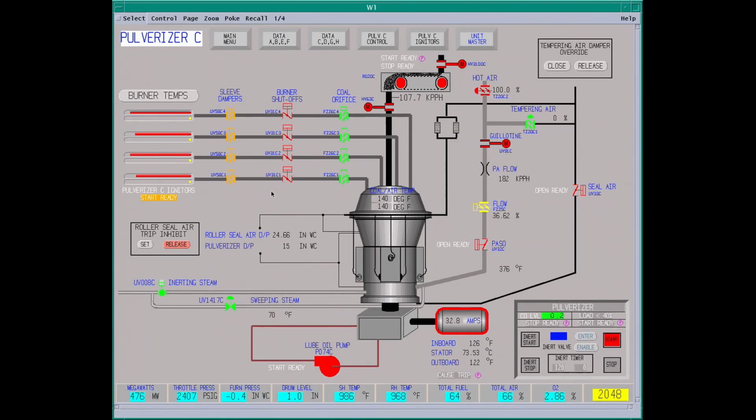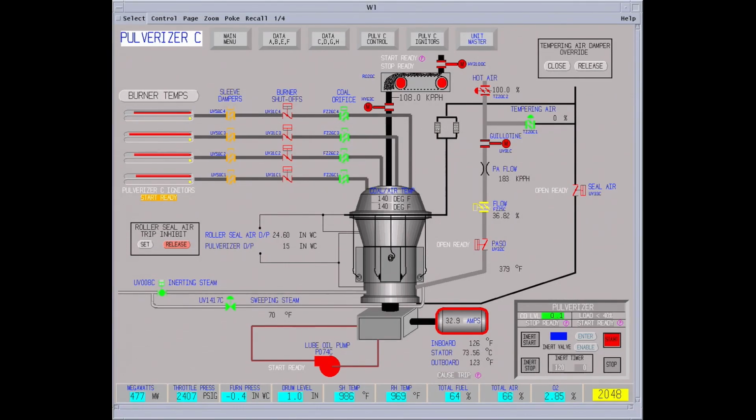But like we started out with, we're sitting right between 2 pulverizer bands. At 4 pulverizers, we couldn't go above 425. And at 5 pulverizers, we couldn't go above 400. So it's kind of a guessing game which way you're going to go. I mean, we could have started in the pulverizer and then went up and not had the block. But if you had 5 running and they want to drop load, then you couldn't go below 400 until you take 5 off.